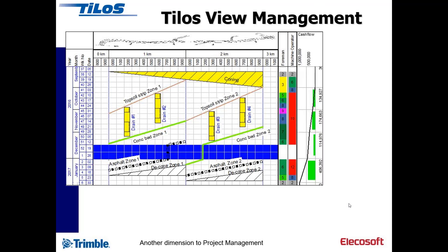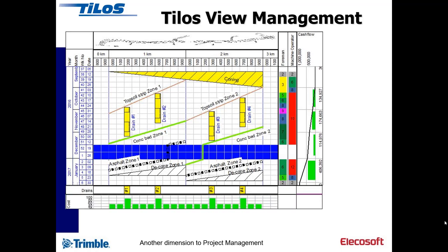You can have graphs where you're seeing a cumulative and a period amount, so you're seeing how much money or profit in total or per month, or that could be man hours of effort, or that could be cubic meters of material. And in the same way, on the distance axis, we can also have irregular objects, such as in this case drains, but that could be stations or overhead line masts on a railway. And on the distance axis, we can also have the same graph. So we can have resource and cost graphs, so you can see how much it costs per kilometer.